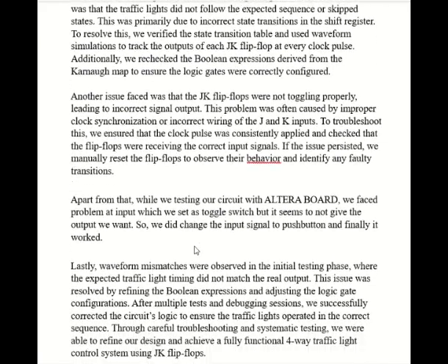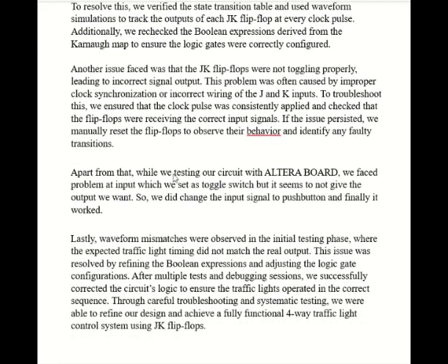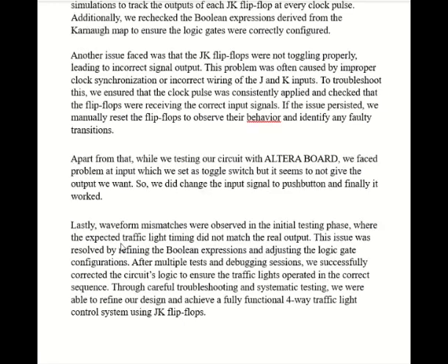transition. Apart from that, while we were testing our circuit with Altera, we faced a problem at the input, which we set as a toggle switch, but it seemed to not give the output we wanted. So we changed the input signal to a push button, and finally it worked.